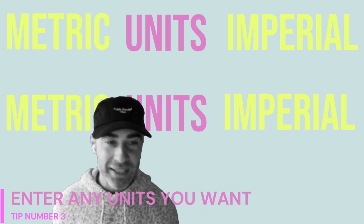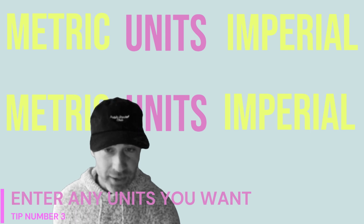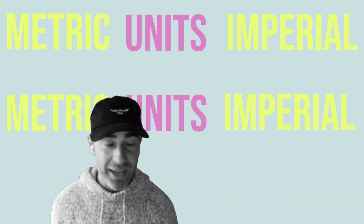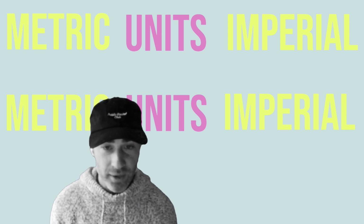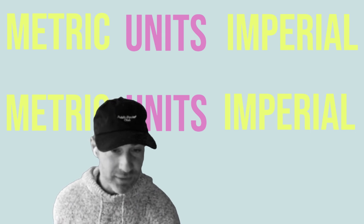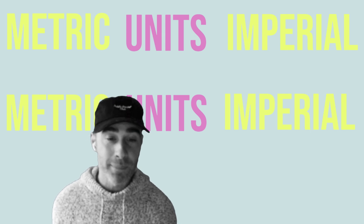Tip number three, enter any units you want. Each model has a default unit that is used when you type a value. However, you can type any units you want. For example, if this is an imperial file that you're working on and you type 152 millimeters, that is the same as typing 6 inches, and Revit automatically knows this.